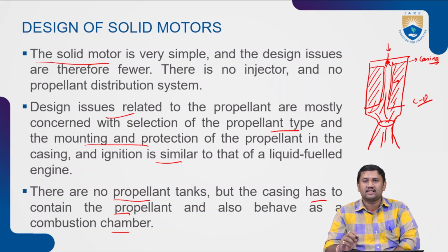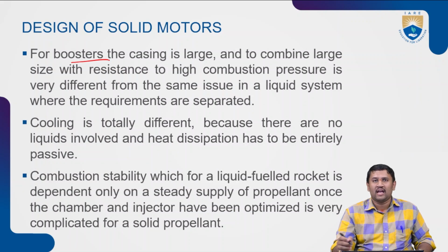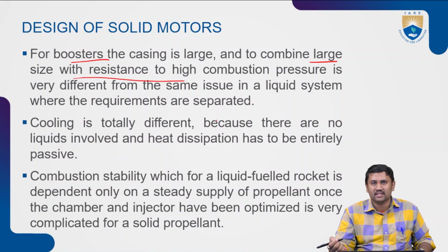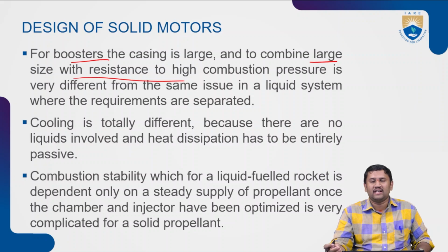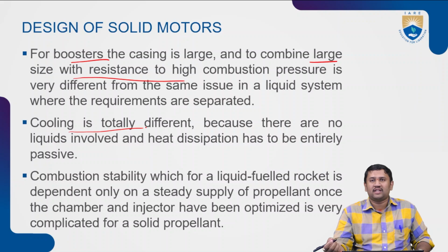Now in this case there are no propellant tanks, but the casing which stores the propellant will also act as a combustion chamber. For boosters the casing is large, and combining the large size with resistance to high combustion pressure is very different from the same issue in the liquid system, where the requirements are separated. The cooling is totally different because there are no liquids involved and the heat dissipation is entirely passive.